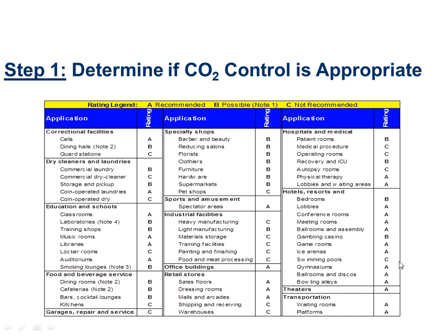Swimming pools we leave alone because of the chlorine, right? And then all the B's are ones that are maybes, depending on what you're doing in there, right? Like I said, a dining room might be a good example, depending on what you're doing with the kitchen for its makeup air, right? Same with the cafeteria. Or a casino might be a good example if it's a non-smoking casino. But if you're allowed to smoke there, probably not a good idea. So there's some of those kind of factors that get involved here.